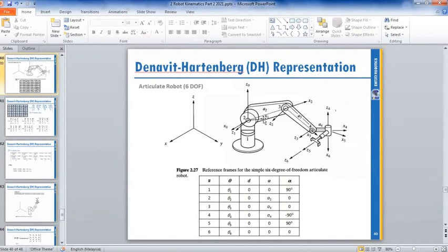If you look from X, you look along the X axis, you see Z rotating from Z0 to Z1 counterclockwise. Right. If you look at number 4, you see from frame 3 to frame 4. Frame 3 you see it horizontal, then frame 4 you see it vertical. So it rotates. You must look through X. Oh, it is reversed again. So clockwise. When it is clockwise it becomes negative 90. In mathematics, if you rotate clockwise it is negative, if you rotate counterclockwise it is positive.